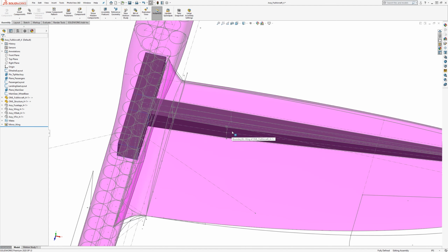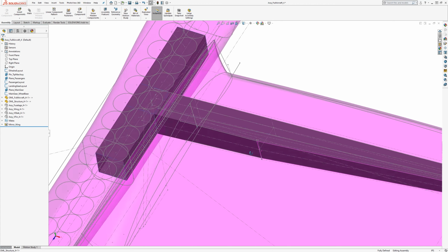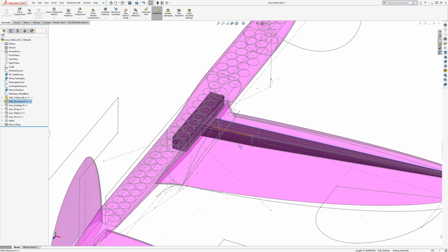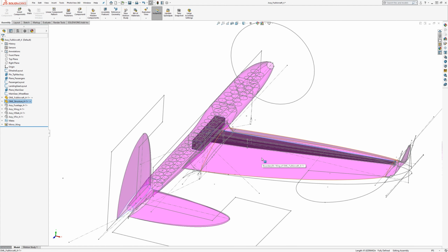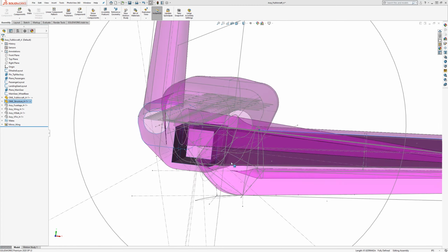So the way that this is referenced later on for the subassemblies will be used to create the actual parts, the fittings that make these structural angle changes, and sort of the sheet that creates the wing skin, and in this case I'm going to use angles as the spar caps. So that's it for the OML structure.